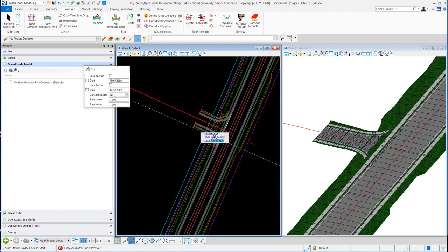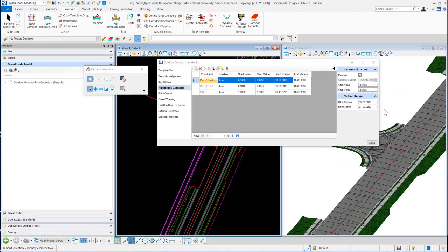If I wasn't making any more changes to this intersection, I'd probably snap to the PC and the PC. That would probably be my beginning and end. But we're going to do a bunch of editing here, so I'm just going to go approximately there and approximately there, and then we'll come back and adjust that later on. Alright, and this should turn off all that through road curb and gutter and sidewalk and end conditions through that intersection there.